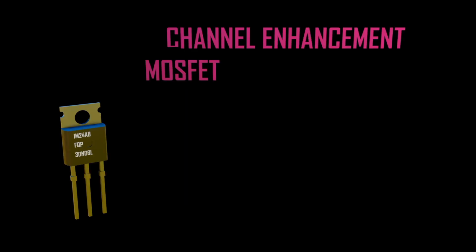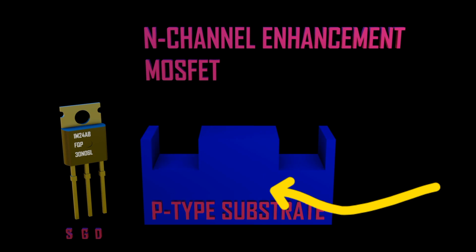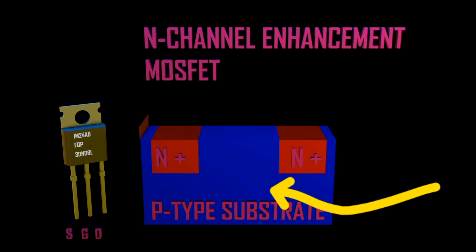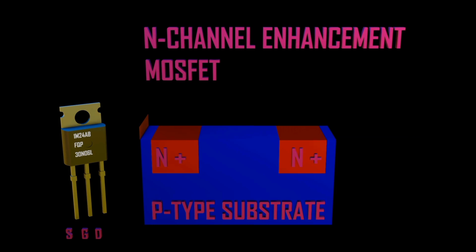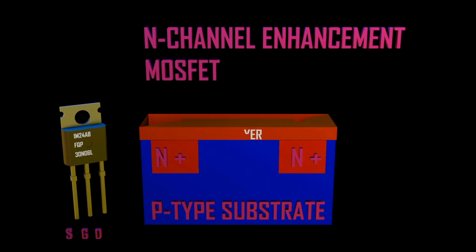Its construction consists of a substrate silicon layer, which is lightly doped, upon which two heavily doped semiconductor materials are laid on top. Then an oxide material is laid on top, to which the terminals source, drain, and gate are attached.